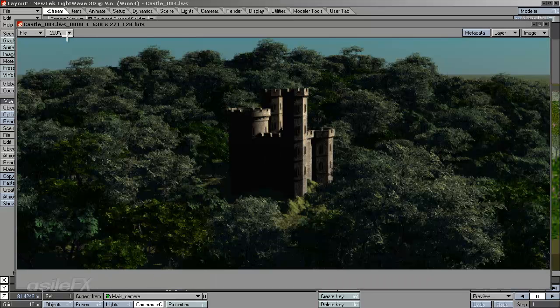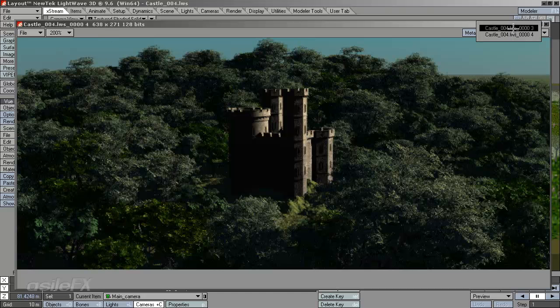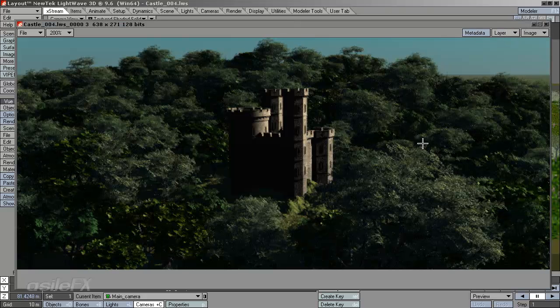Okay, so I'm viewing this at 200%, so it's very pixelated. So it's double the size it actually rendered at. I've got two frames I rendered out. One, this is with that texture filtering set to 33, which is the recommended amount, especially for animation. What it does is it basically is a mid blur in a way. It'll blur out textures in order to smooth them, and a lot of flickering is caused by the intersecting of polygons from highlights.